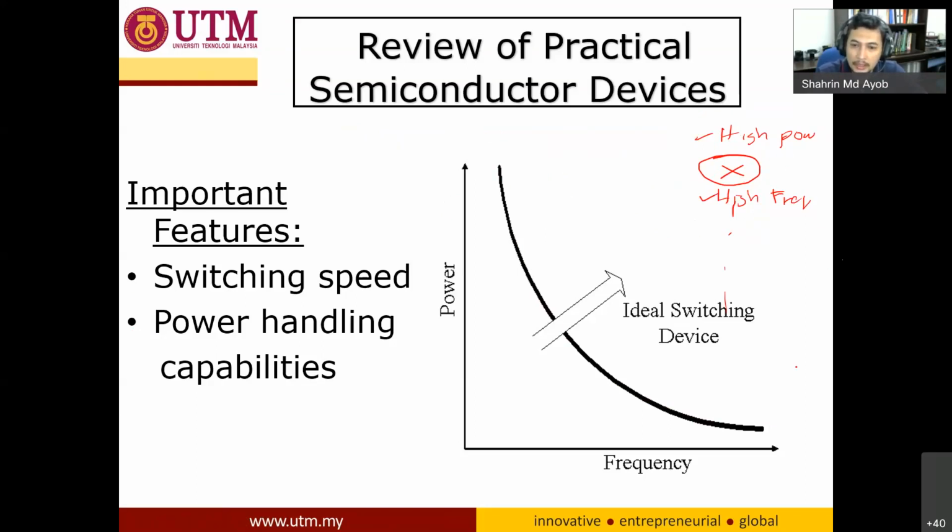The devices available in the market are either capable of handling high frequency, but the limitation is that they cannot handle high power. Or, as you can see here, some devices can go to high power but with very low switching frequency. So there is no such device that is capable of fulfilling these two requirements, high power and high frequency.